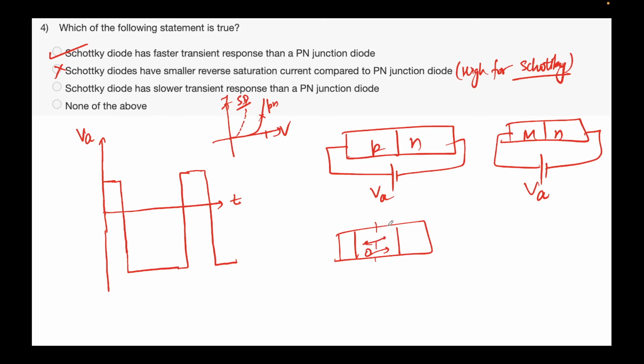So they can flush out all these charges, and the depletion region cannot have any mobile charge carriers. Please remember that in the forward bias, there will be a drifting of electrons and holes, but when you switch to the reverse bias, it cannot be there.